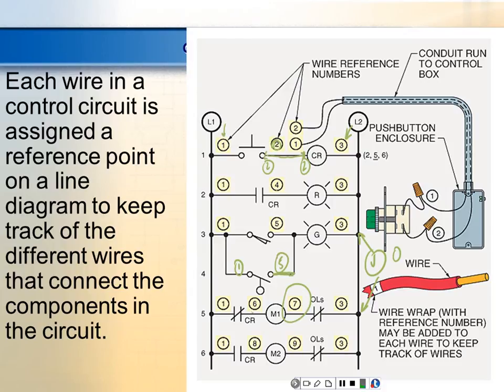And man, when you get into industry, if you work on a motor control circuit, odds are the only color-coded wires you're going to see are in cables. All these other wires are going to be in these little plastic wire troughs. They use them to arrange them. We got some in here somewhere. They're going to come poking out, and they're going to hook up to a terminal board. At the terminal board should be the wire number. I've seen it 2 different ways. They put the number on the actual terminal block itself, which is good, but I like to put it on the wire.